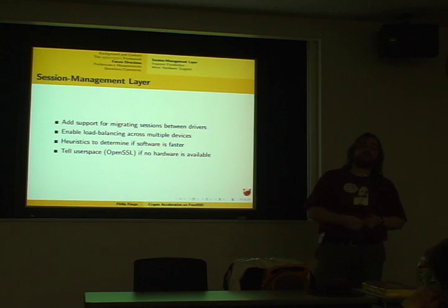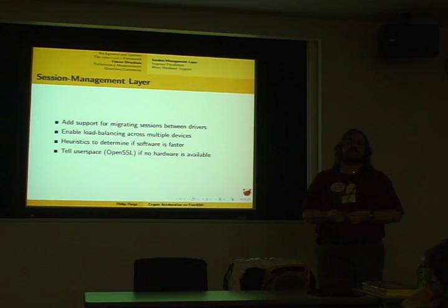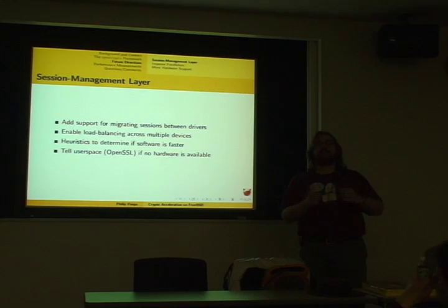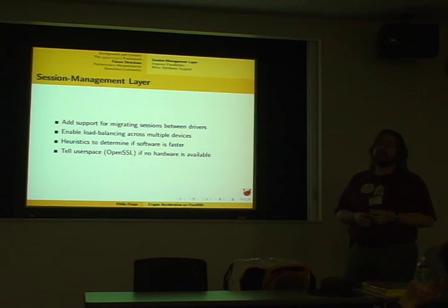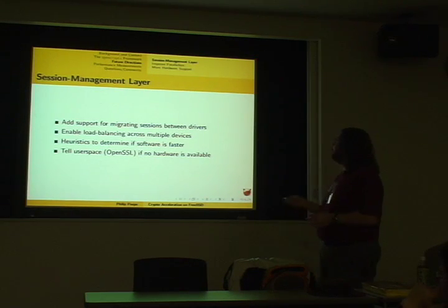A number of embedded CPUs have got crypto blocks in silicon, which are good as long as you have fixed size keys and your operations are a fixed number of bytes. But if you've got anything different, it's going to be slower. So then I would like to say use the software crypto, it's going to be faster. And I'd like to do the load balancing.